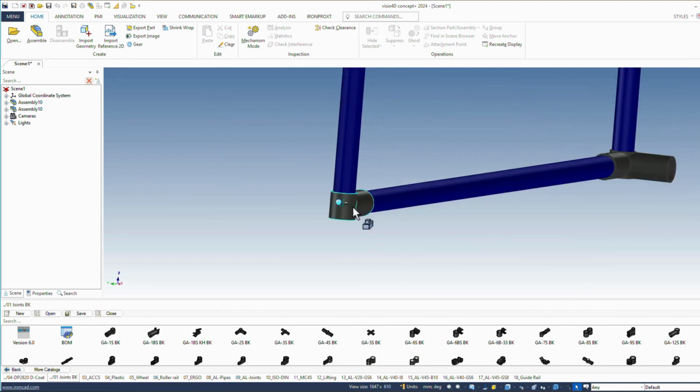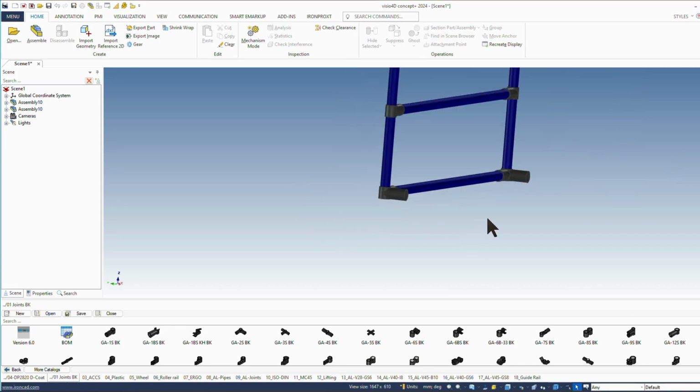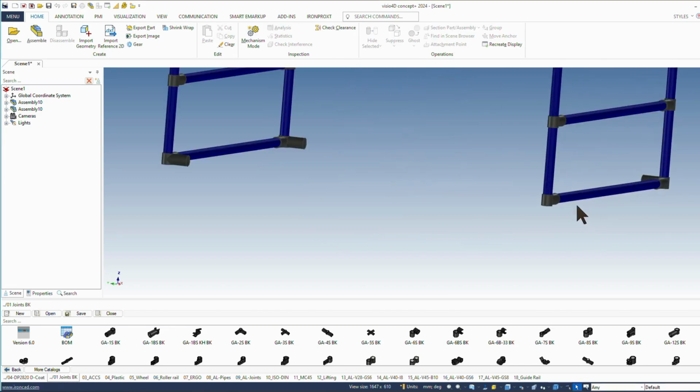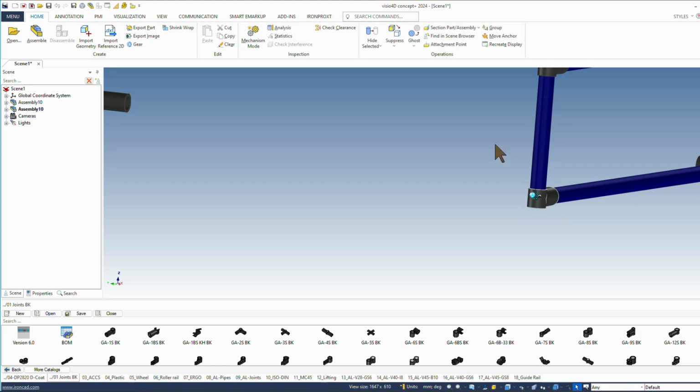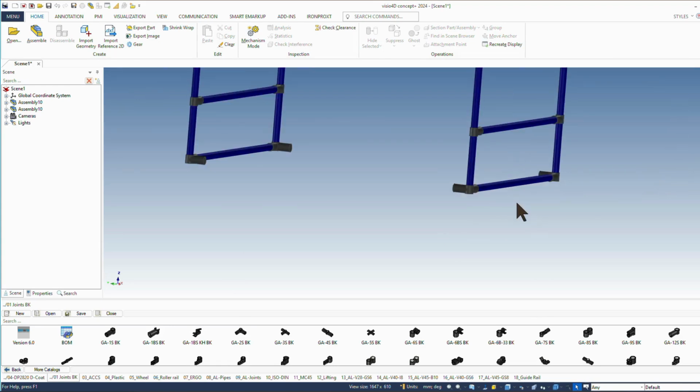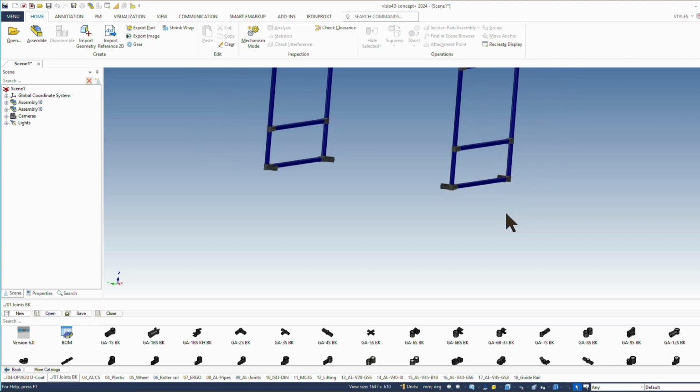I'll do the same over here. Press the Control button, move up to the joints, swap GA2S, triball, select the swivel axis, hold down the control button, swivel once, switch off the triball, place the control button on the components, switch on triball, select pivot axis, press the control button. I suppose I did that wrong because I don't need to pivot just yet. I just need to swap them. Tap on it, swap. I don't need to pivot at all.